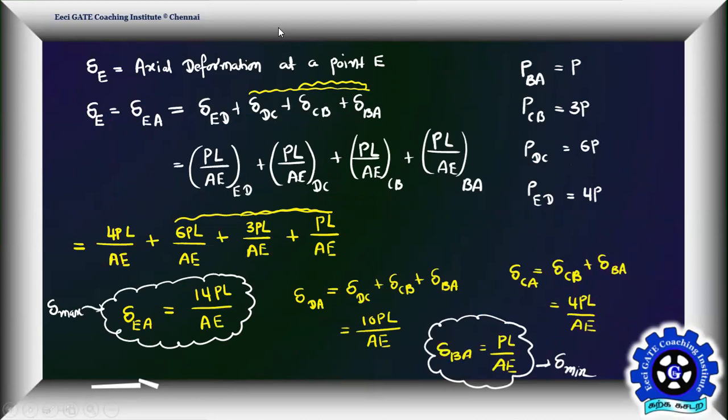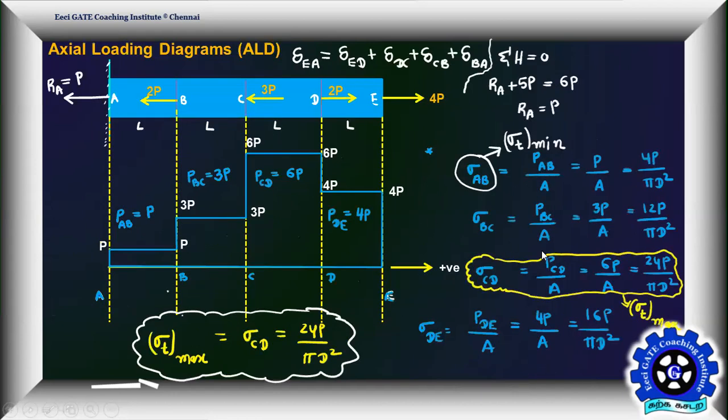Balaji, please tell me. Yeah, you asked a doubt. What if the member is made up of a different material? Okay, no issue. Stresses won't change. Stress is independent of the material. It depends on the load and area of cross section. Different material in the sense here.